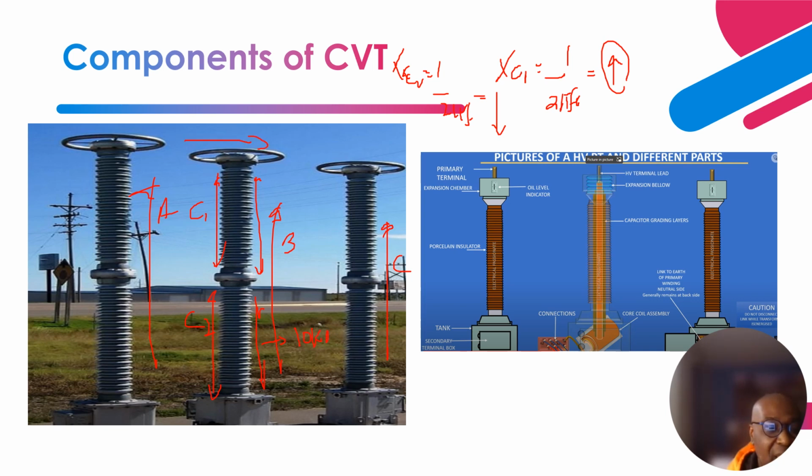Remember, we are coming in from the line level at 115 kV, 230 kV, 345 kV, 500 kV, 765 kV, right? And as a matter of fact, now they are at 1100 kV. And we are able to step it down to 10 kV utilizing a capacitive voltage divider, right? So this becomes an input into the electromagnetic unit. The electromagnetic unit is located here. So that is why we have a step down transformer, right?